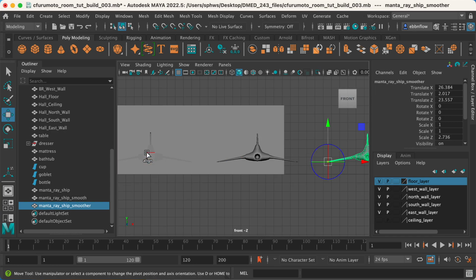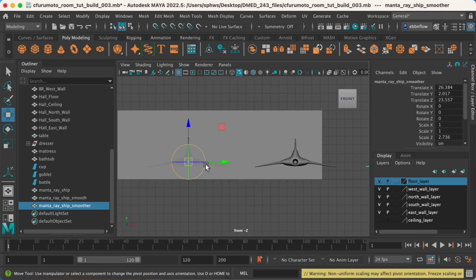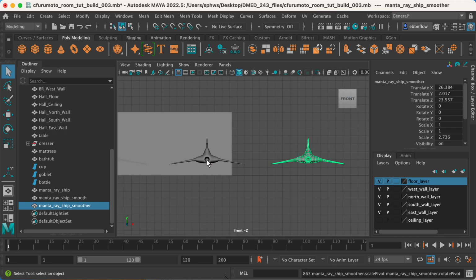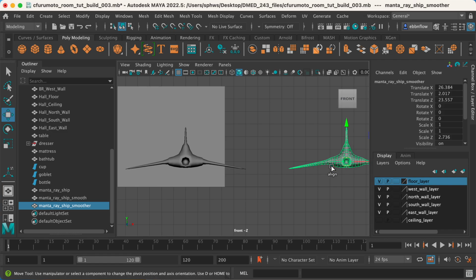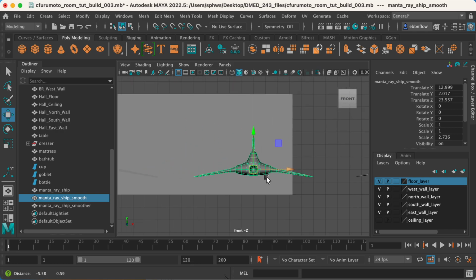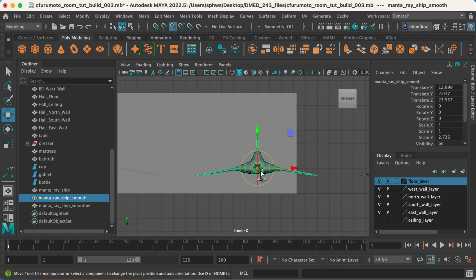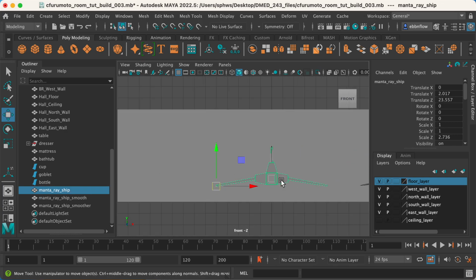Okay, and then we can pretty much snap these to the ground as well. So, oh shoot, I keep moving the pivot point to the wrong spot. So D, V, sorry, D, V, snap that to the corner, and then D. So I'm not jumping out of the tool correctly. Again, D, V, snap it to the corner, D to get out. Okay, and then let me double check on that one. That looks good.